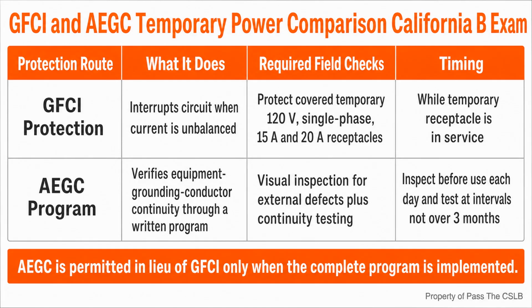Flexible cords smaller than American wire gauge number 12 cannot be spliced. A hard service cord that is American wire gauge number 12 or physically larger may be repaired by splicing only when the repair restores the cord's original insulation, outer sheath, usage characteristics, and dielectric qualities. Electrical tape wrapped around a damaged spot does not automatically restore those properties. Tape can hide the defect while leaving the mechanical strength and insulation performance unresolved.